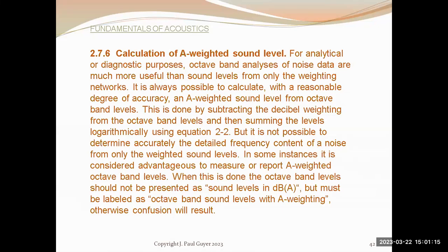In other words, you go in and you look down at the sound level meter, and you see it says such and such decibels, and you write that down on your clipboard, and then you wait 15 seconds or 30 seconds or a minute, and then you look down at the meter and you read it again. You record that decibel level, and you keep doing this. So there's the meter sampling the sound and you sampling the meter.